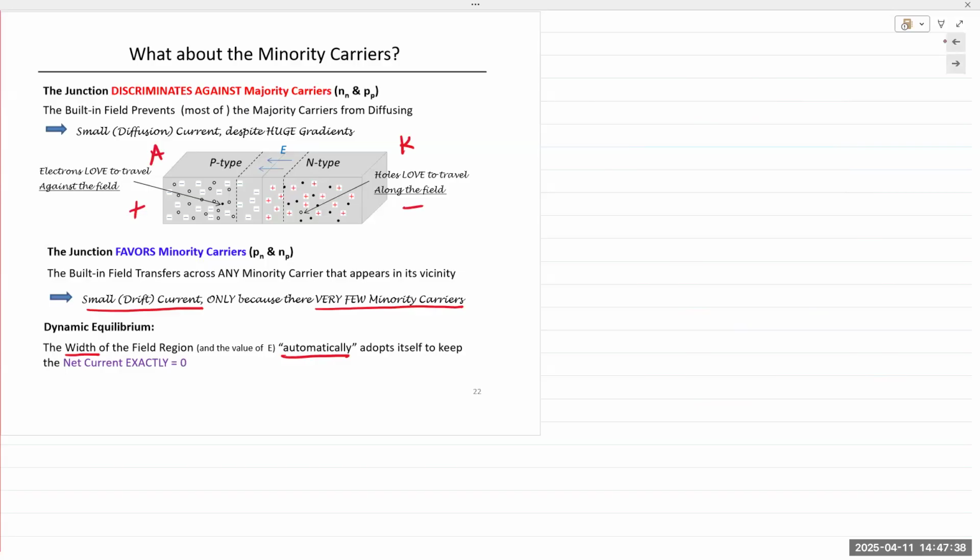Positive charges repel, opposite charges attract. So it's going to repel the holes, go in this direction. Same thing happens to the electrons. They're now moving towards the junction. But the junction is, let's just say 0.7 volts, for instance, right? So you apply an external voltage of 0.1, 0.2, 0.3, 0.4, 0.5 volts. You won't see much happening until you reach like 0.5 or 0.6 volts.